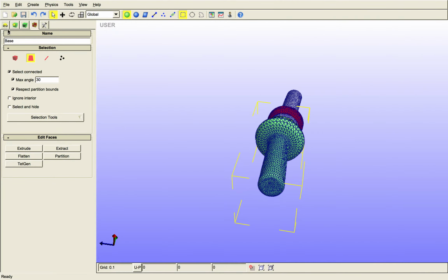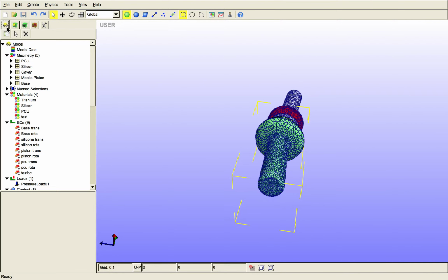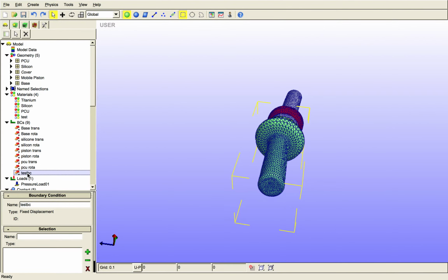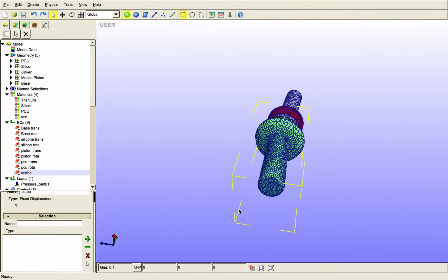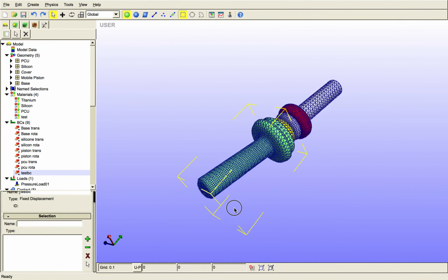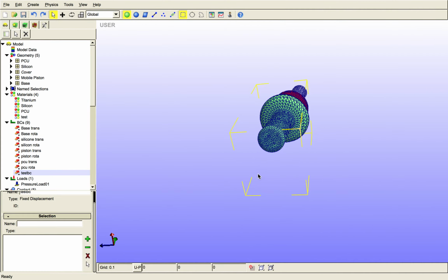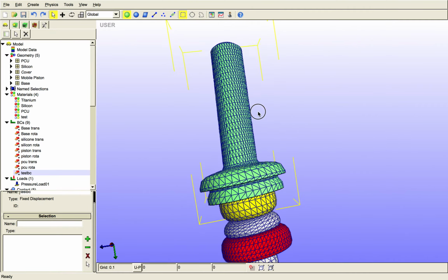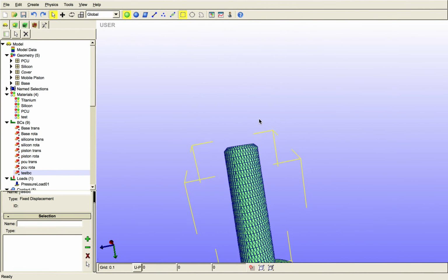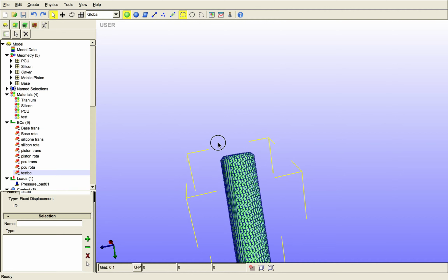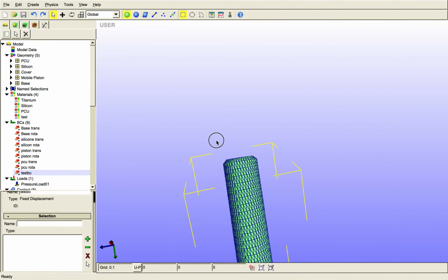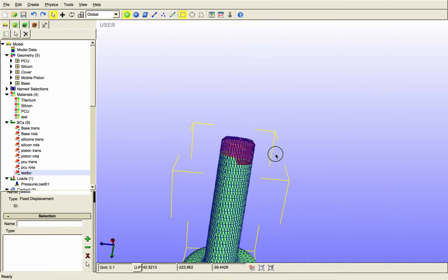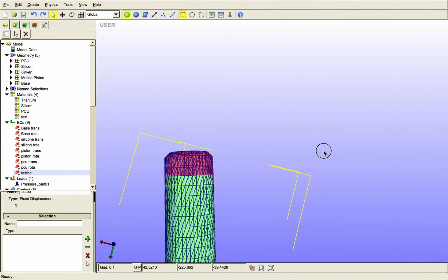and from now you can come back to the initial window and to the test boundary condition, and here you can select element by element. Let's suppose I want to block this area. I'm just going to zoom on it. I can select it using the mouse and pressing the shift button in the same way, and here you go, you have selected element by element, which is really counterintuitive compared to Abaqus, I know, but this is how it works.